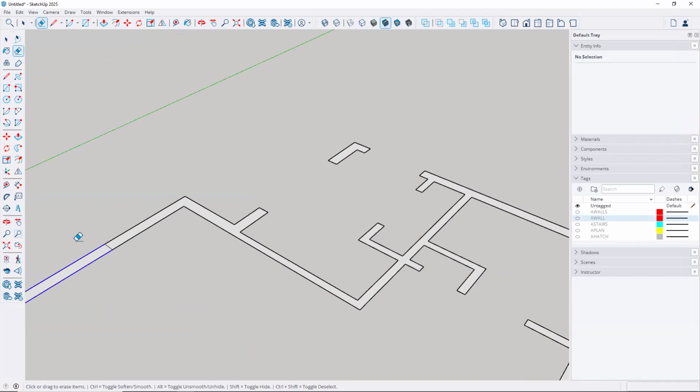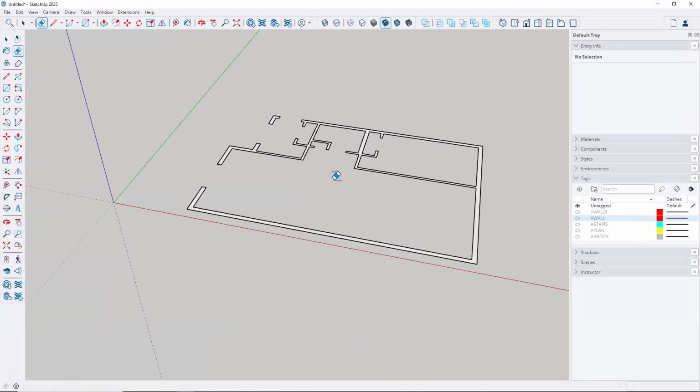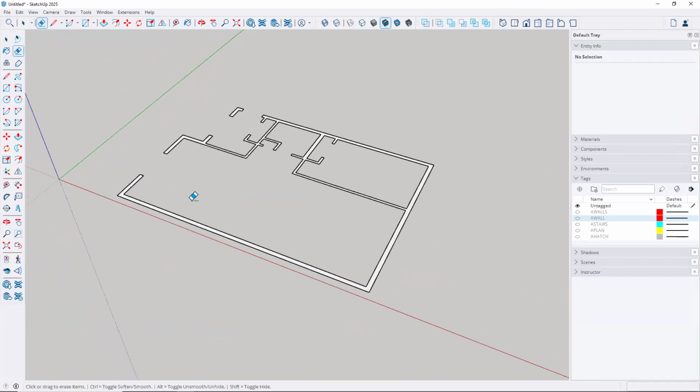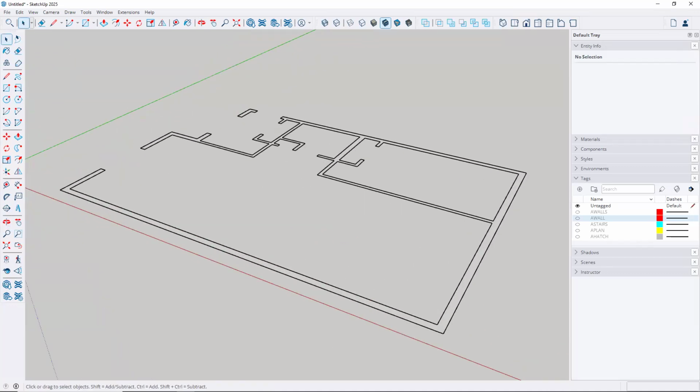There we go. Spacebar, turn off my walls, and then E for erase, and just erase the openings here, like that, and click and drag across. So that's another way of doing it. And I'll tell you what, I know I said I was going to separate my walls. I'll keep them together for now. But it works either way. Doing the exterior separate from the interior, it's fine. Let me tap the space bar, and now would be a good time to save. So Control S to save.